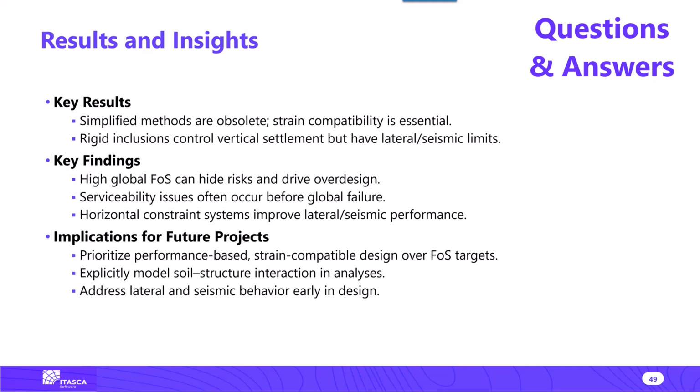So essentially, if you're using a low failure ratio, the curves become stiffer, and the other way around. I tend to use an Rf in the order of between 0.8 and 0.9. So I tend to fix that parameter and then play with the others to get what I need. Otherwise, there are too many variables moving at the same time, and it becomes a little bit difficult.